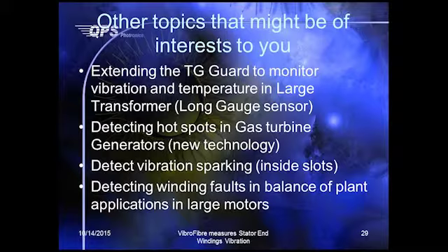This is a situation where the conducting paint, carbon paint, over the insulating layer on the winding, due to vibration, loses contact to ground, and then momentarily has high voltage, causing discharge.